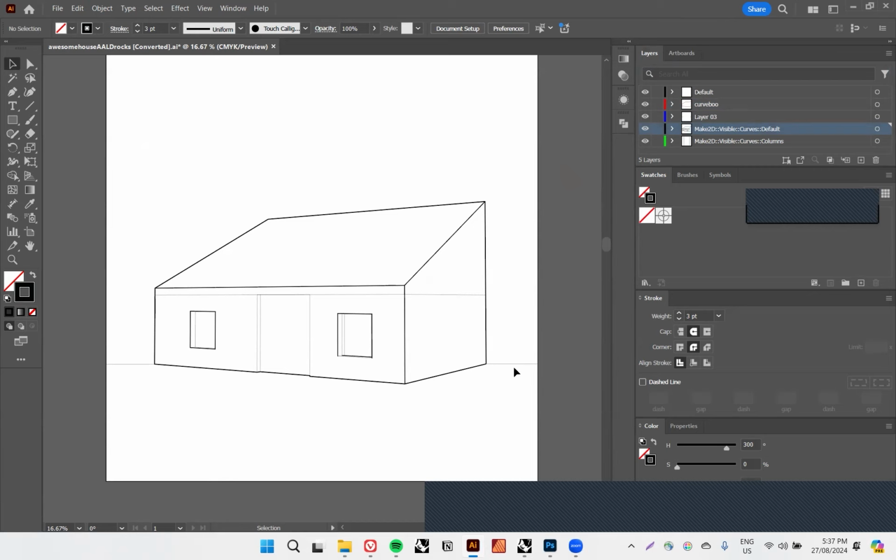Let's make the ground floor plane. If you're doing a section cut, you guys are going to be doing a lot of section drawings. That's when you cut through a building. Your thickest line is always going to be your ground floor plane, the floor you're cutting through. And then you're going to have a thick poche or thick cut lines through the floors and the walls that you're cutting through. But we're not doing a section, but I'm just going to make the floor a little thicker.